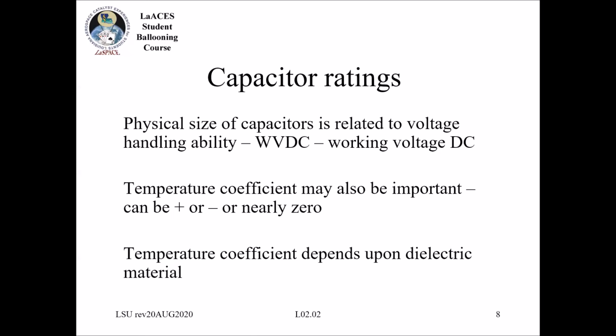The arrow usually is the direction of the current that it flows. The other thing I wanted to talk about here real quick regarding the capacitor ratings, Jill just talked a bit about how you always want to pick capacitors that are double or sometimes even more the actual value. And I want to tell you the reason why. You might think, we're just working with DC voltages all the time, but the reality is DC is really rare to actually see, and everything's not